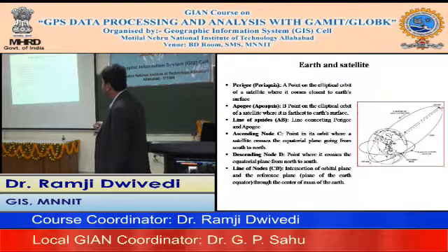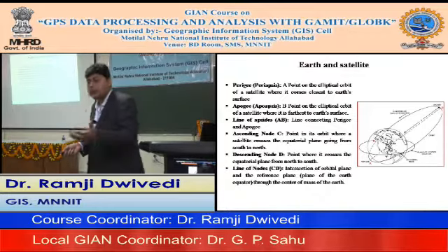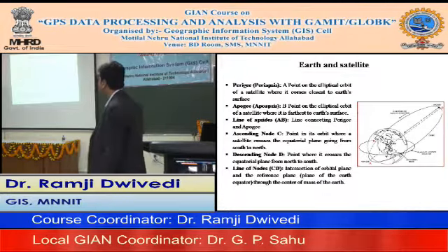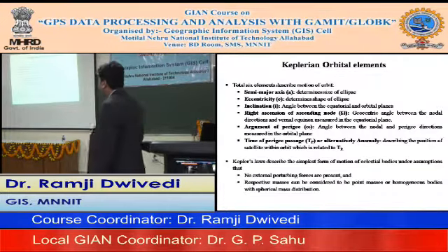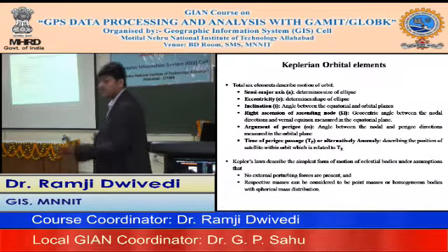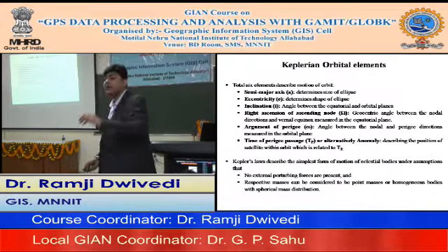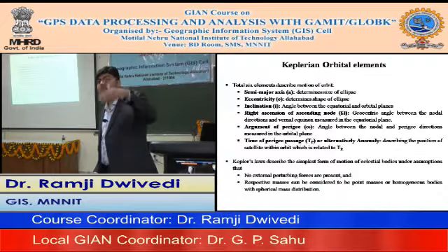These are the Keplerian parameters given by the satellite through the navigation message: the semi-major axis of the orbit where the GPS satellite is presently moving, the eccentricity of that ellipse, the inclination with respect to the equatorial plane of the orbit, and the right ascension. As I said, right ascension is measured in an ECI system, which is the Earth Centered Inertial system.